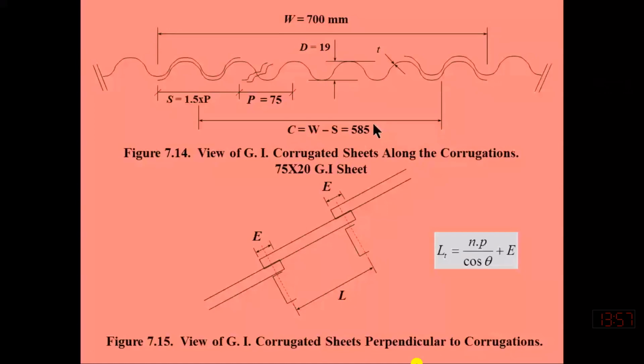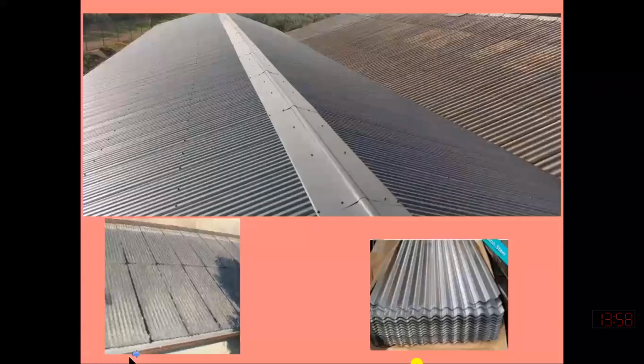Similarly, this is along the width, and along the length we are providing the roof sheet as an incline. So here from this diagram, I am just showing this length. We are placing one sheet along the length of the top chord, in the perpendicular direction to the purlin, and then the other sheet. So first of all, we place the sheet this way.